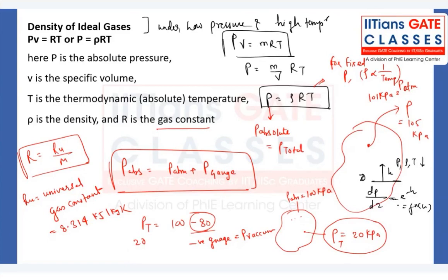Now, all of you have noted down. For air, if I ask what is the R value, you might be using the R value frequently in gas dynamics. Tell me guys, 8.314 divided by the air molecular mass, 28.97, we treat it. So almost, what is the value? 8.314 divided by 28.97 is 0.287 approximately, right? Kilojoule per kg Kelvin. 287 is joule per kg Kelvin, right? Yes or no, guys? Getting my point? All of you.